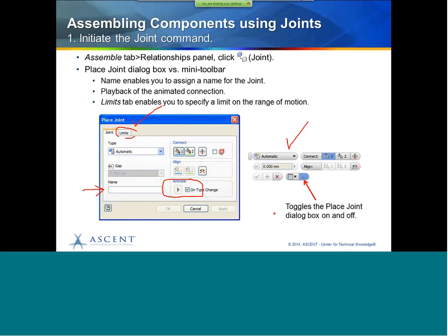And finally, limits, and this is a fantastic option. So in that slider option that we talked about, the animation showed a little range of motion which maintained within the actual physical part. However, in actual fact, that could actually drag right through my model, so it doesn't recognize interference. So with that Limits tab, you can do that. You can set range.